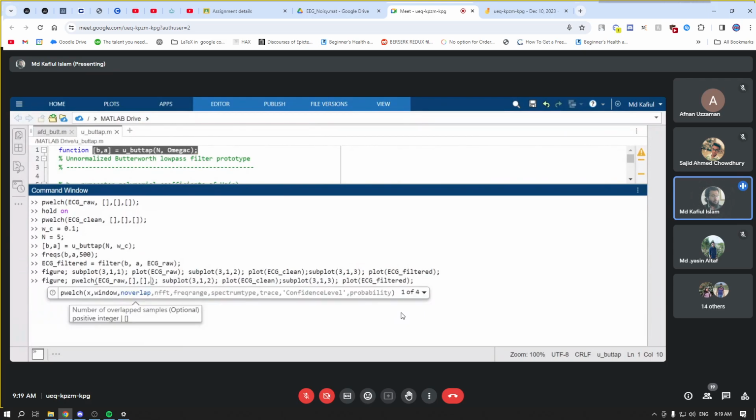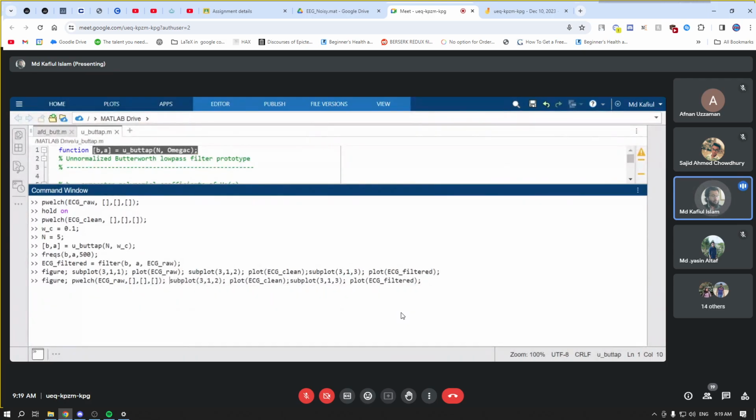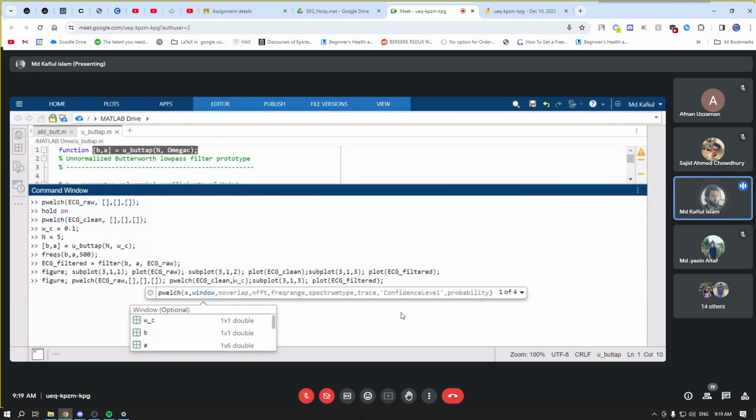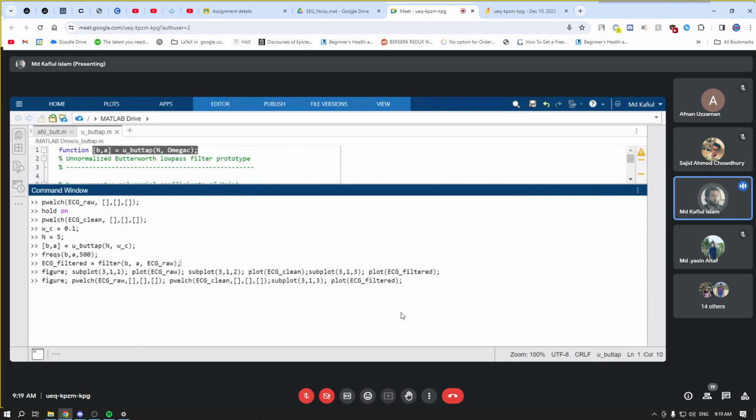Remember that we did not know our sampling rate. Sampling frequency was not given, and we did not use it yet. So maybe we need that sampling frequency information, otherwise we may not be able to design the appropriate filter. But let us first see how the signal looks in frequency domain, because that is what we have missed so far.